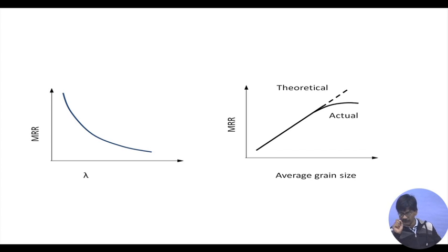So, in the average case it is found that there is again the crushing tendency coming in. When the grains become very large in size, they have a tendency to get crushed and they have a difficulty to enter the machining zone, because they are so large in size compared to the amplitude.